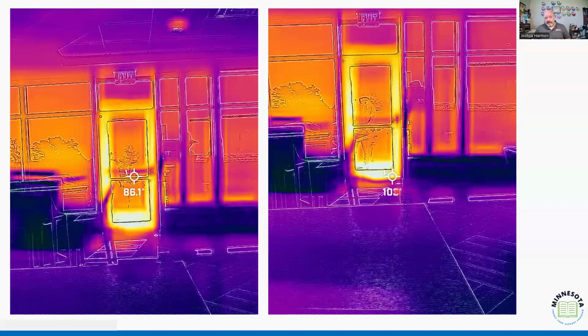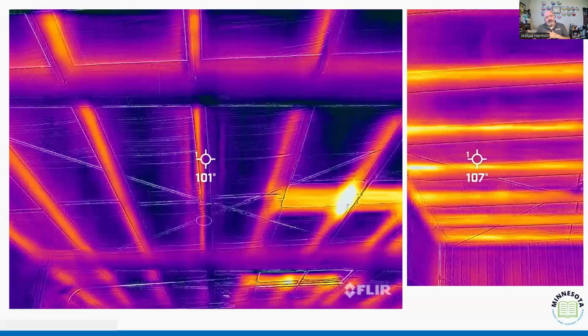And then when it gets to be cold outside, that air is going to move out through that same hole. Again, remember, if we talk about the example of a steel structure, right? If we don't have proper thermal breaks on those steel members, then again, we have uncontrolled heat, thermal bridging coming into the building, and then the air handling system is going to have to compensate for that.